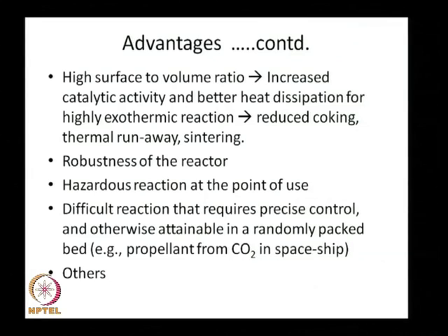So, you want reduced coking, reduced thermal runaway, reduced sintering, and for this purpose, if you can have a structured catalyst, that means channels whose dimensions are all uniform everywhere.